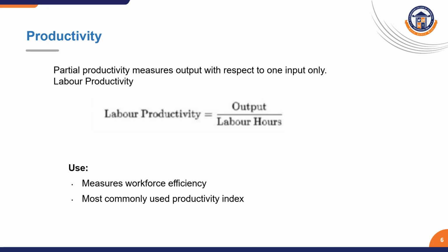Again, the same thing is shown in this slide, output, but here there is something known as productivity indices. What is labor productivity? 1,000 shirts for how many labor hours? I'm assuming I have 100 machines, so I need 100 operators. Each operator works for 8 hours, so it is 800 hours.